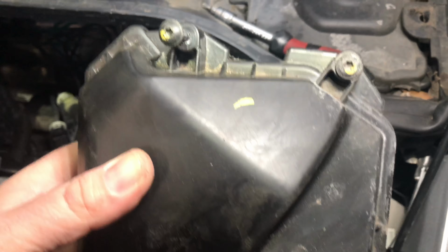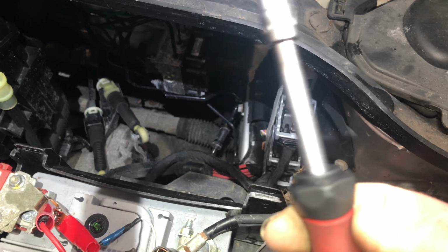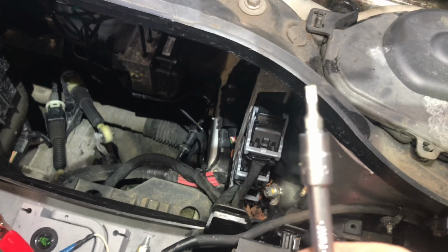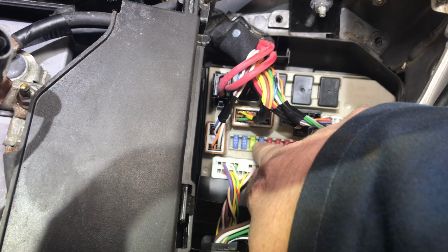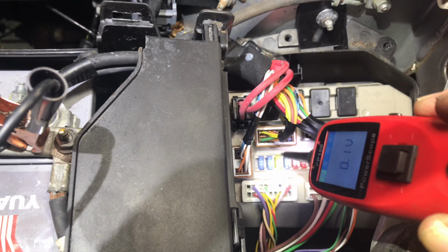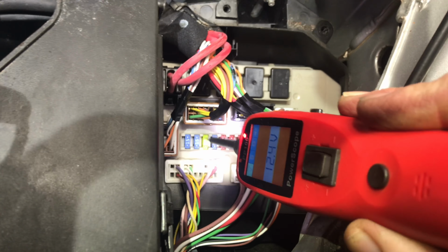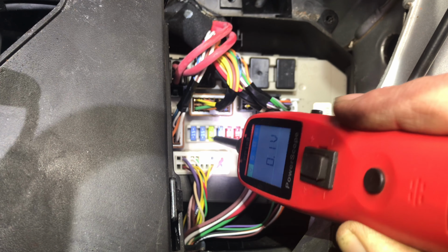And there's 2 Torx. I think these are T... let's see. Size of these. T20 Torx. If that thing would focus. So this is a little chap here that controls the wiper motor. So we'll take our power probe and we'll go to one side. You see we've got something there. When we go to the other side, we've got nothing there. So we'll go and pull it out.